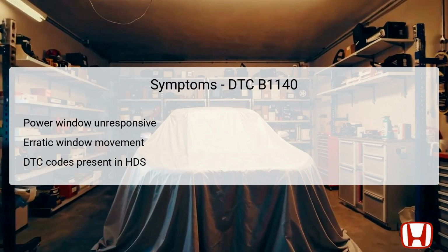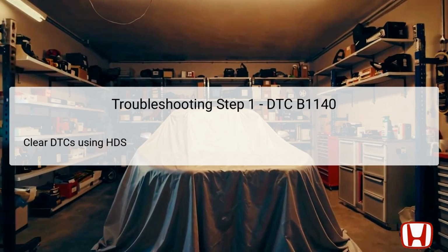The first step in troubleshooting DTC B1140 is to clear the diagnostic trouble codes using the Honda Diagnostic System, or HDS. Clearing the DTC ensures that you're working with a clean slate and not interpreting past errors that may no longer be relevant. This step is crucial, especially if multiple DTCs are being reported, as it allows you to focus on current issues.